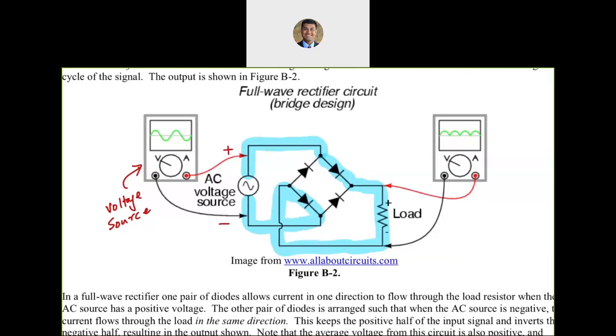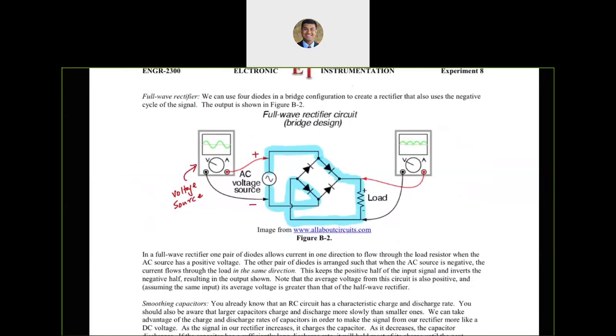And that's going to be a complete loop. Two diodes are being used here, and the voltage across the load, V load in this case, is simply going to be the voltage across the source minus 1.4, because we used two forward biased diodes over there. So that's as far as the positive half cycles are concerned.